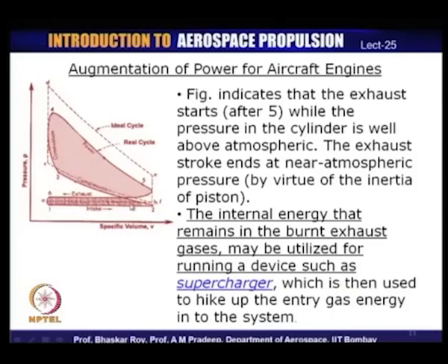So that this intake exhaust loop again becomes a small one and does not take away a lot of power, and as a result the BHP available would again become a reasonable value for supplying power to the propeller. So, supercharging is something we will look into in some detail in the next class,